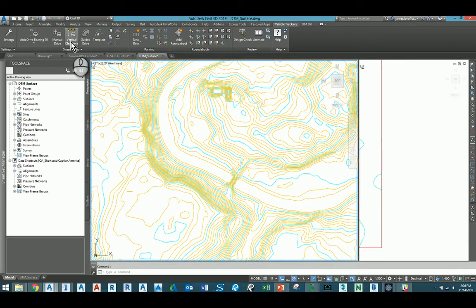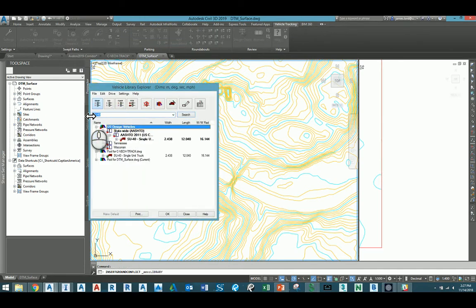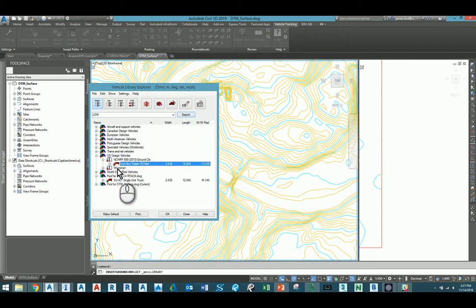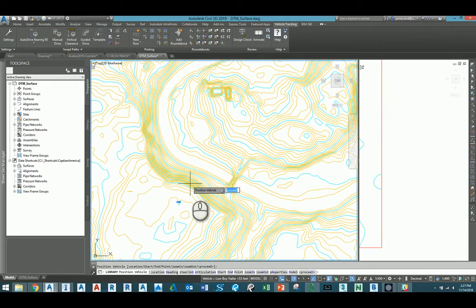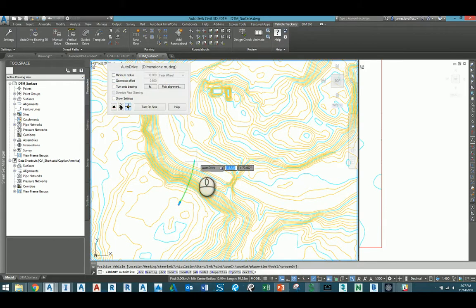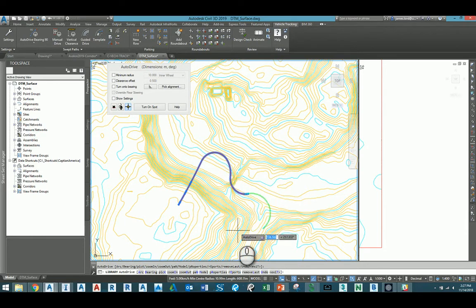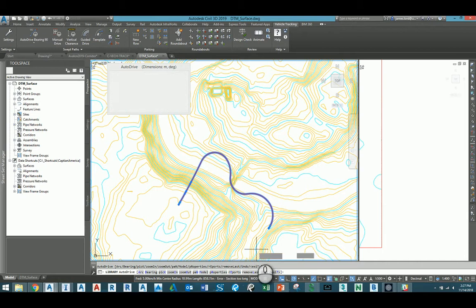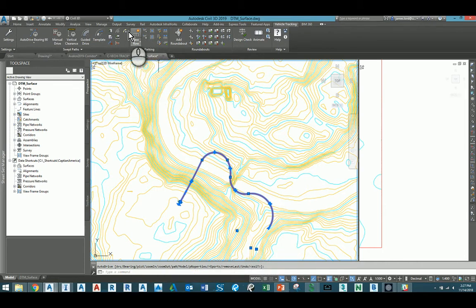there's one other feature you should be aware of, is the fact that you can do a terrain analysis from this. So you can just do a ground conflict report. You need a path first. Let me just select a really large truck. Let's go with the low boy. I believe he is the longest one inside of this program. And then let's put in proceed. Let's go through here, here, and there. And let's call that an end.